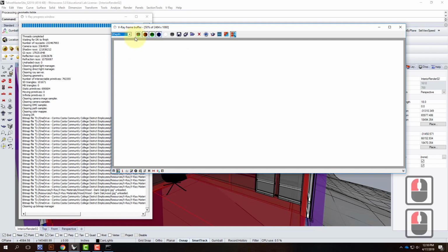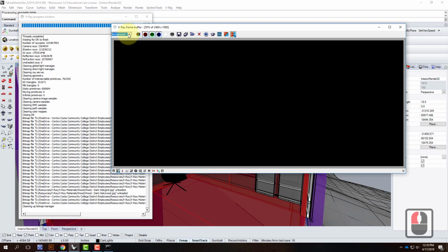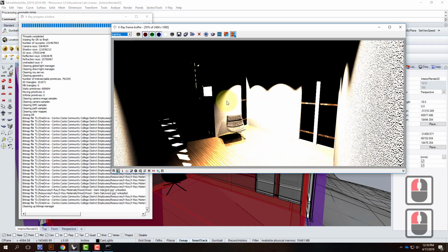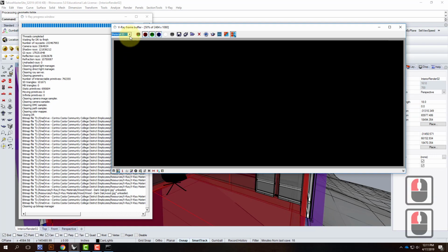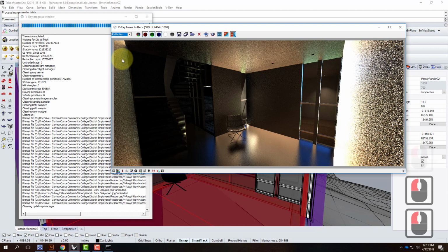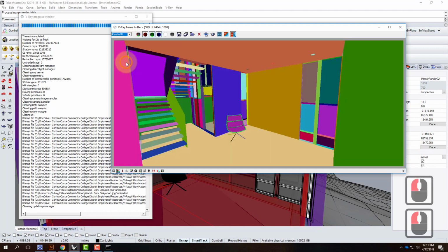Z-depth, nothing showing here. I'll do a tutorial on Z-depth later on in the semester, but you might as well turn it on anyway. Background, in my case, everything's inside. If I had the exterior render, I'd see just the background here. Lighting is giving me where just the lighting is, which can be useful to enhance it in Photoshop afterward if we wanted to. Material ID didn't give me anything. Let's try reflection. There we go. These are reflections, just seeing the parts that are reflected.